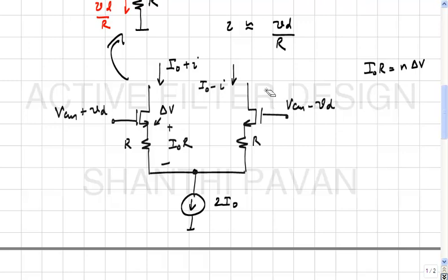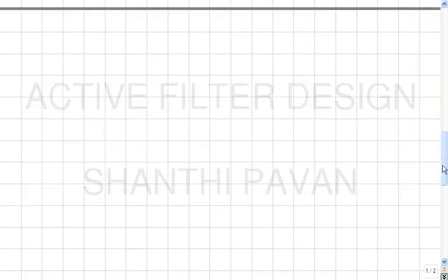All right. Now, what do you think happens to noise? There is the noise due to the tail current source. Is it of consequence or is it of no consequence? No consequence, because it splits equally and is only adding to the common mode noise. Differentially, it doesn't matter because it's the same on both sides. Okay. So, as far as differential noise performance is concerned, we just will be happy to look at the differential mode equivalent.